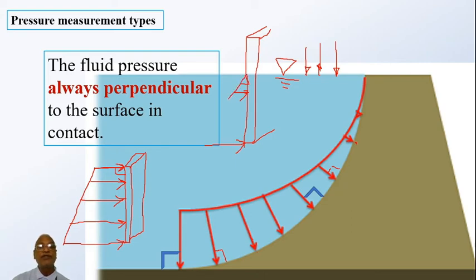Now all these pressure intensities, if I join, again you will be getting a straight line. As I have told you, gamma multiplied by depth gives you intensity of pressure. So at any intermediate depth also you will be getting pressure intensity, right? Why it is gamma z, we'll be seeing at a later stage.